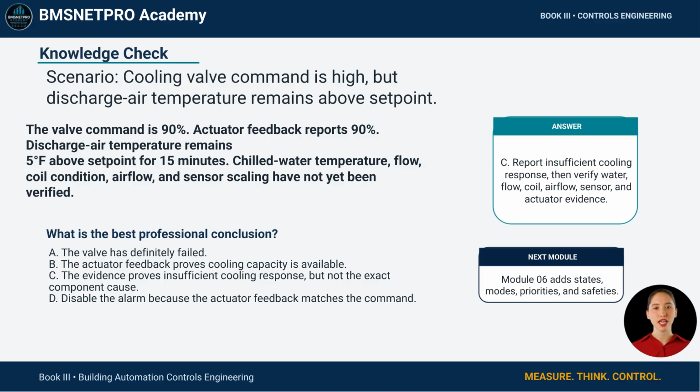Use this knowledge check to reinforce the difference between evidence and diagnosis. The best answer is C. The BAS has evidence of insufficient cooling response, but it has not proven the exact component cause.